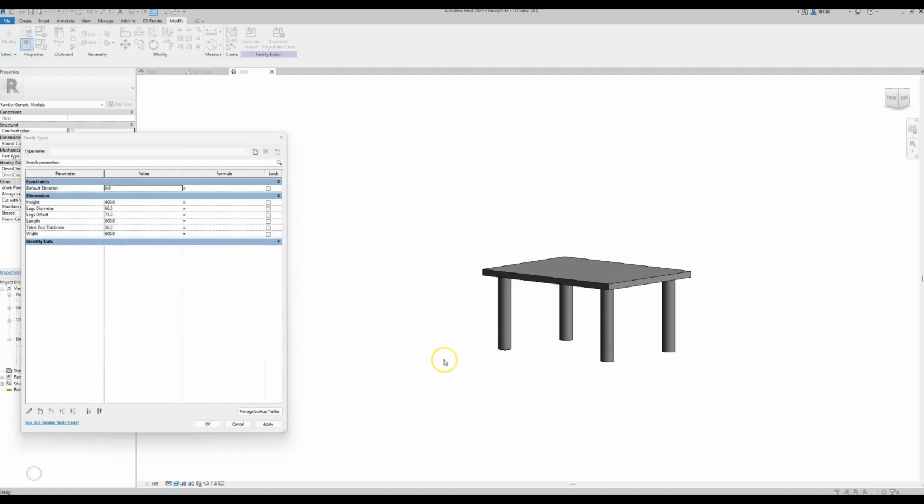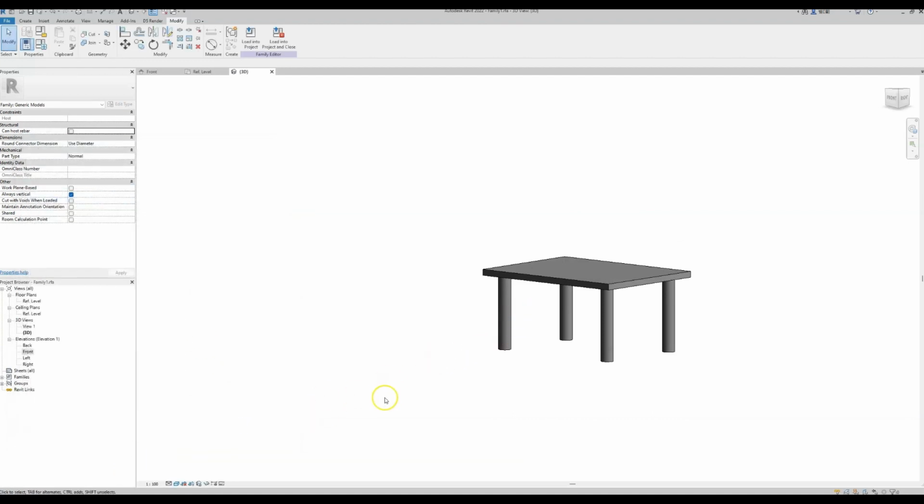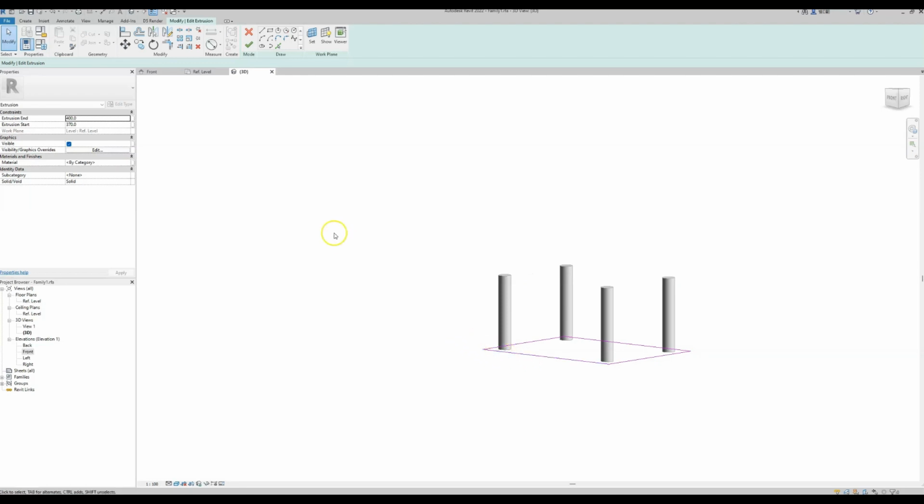Okay. Looking at our 3D model, we realized that this is a kid's table and it's not wise to have sharp edges for the tabletop. What we need to do is edit this extruded surface and change its perimeter with a nice rounded edge. How to edit the already extruded surface? Just double click on the actual surface, and now we are in the edit mode.